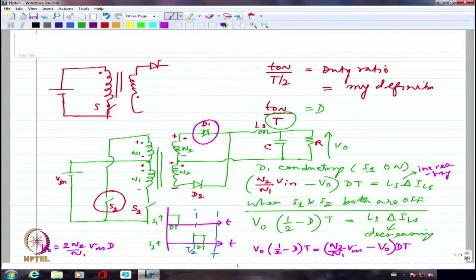So this kind of one diode conduction is what we talked about earlier. In power supplies, what we worry about is the drop. If the output is only 5 volts, you don't want to have 1.4 volts as the drop. That's the reason why we don't use a bridge rectifier. If you use a bridge rectifier, 2 diodes will come into the conduction path, and you want to avoid it. That's the reason why we normally use this, although the voltage rating becomes much higher.